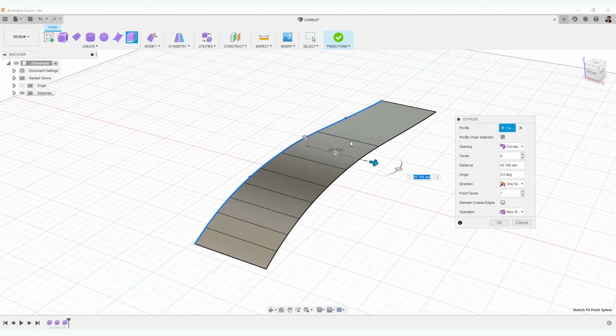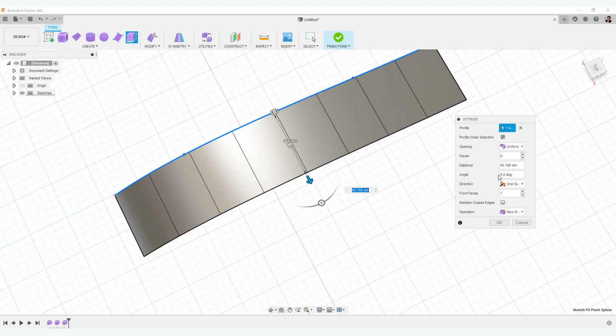The pitch of the faces is not uniform in this way. Edges are placed in the parts of the curvature. Select Uniform from Spacing in the Options window. As you can see, the pitch has changed uniformly.